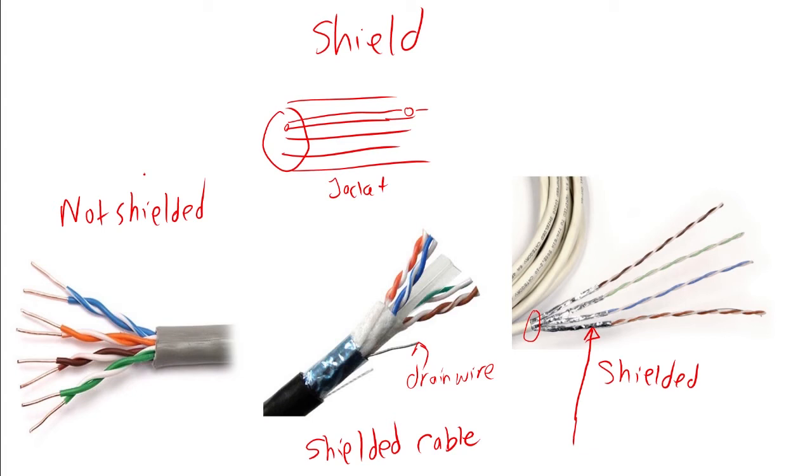So when we have a light bulb or whatever causing our radiation, the PVC material doesn't help us very much, whereas the shielded cable does. Shielded cable is really good when we can't afford any noise or where we want this cable to perform better than the stated characteristics.